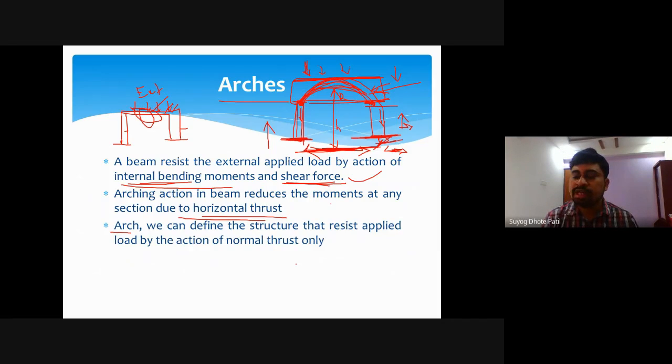Calculate the nature of that application of forces, and we can calculate to what extent those forces can be neutralized. But in the case of arches, we calculate the support reaction. In the case of a parabolic arch, we consider it just like a simply supported beam, a horizontal beam with a number of forces applied on that arch. Analyze as per that.